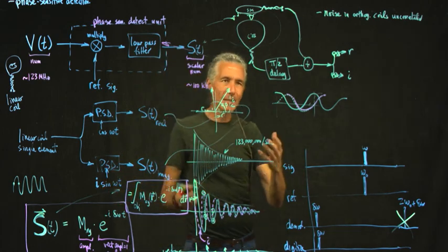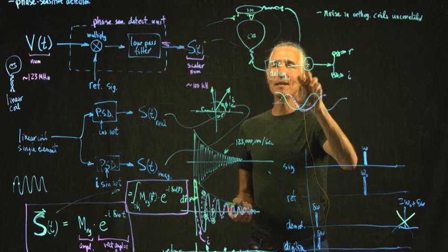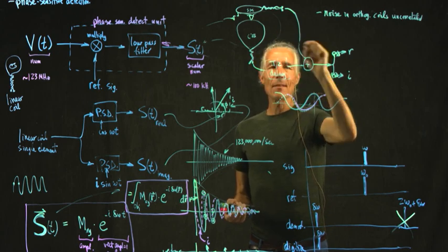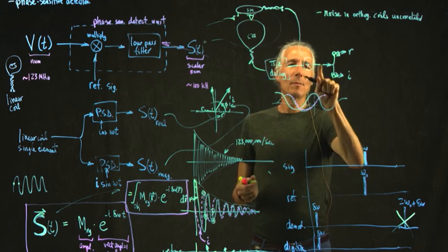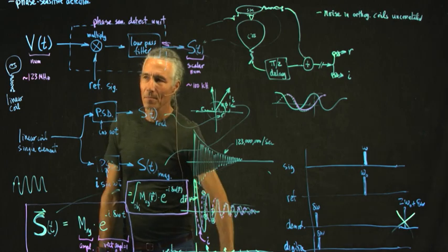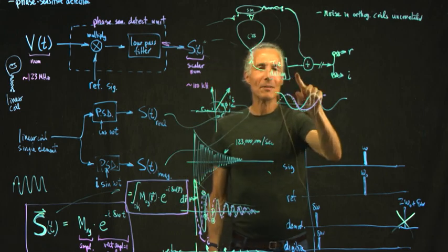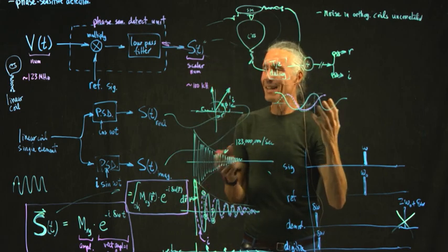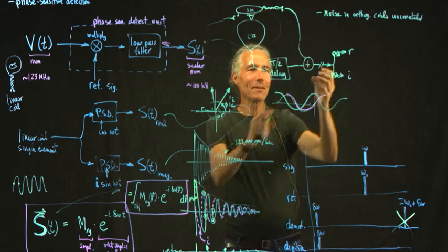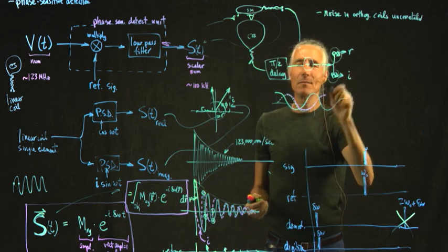So this is the way you might hook up a quadrature coil, and the reason is you just want to minimize the number of wires, because if you delay them and add them together, then you only have one. This could be a long wire heading to the phase-sensitive detection, and so you only have one wire. So you can understand that one. When somebody first said that this is the way it works, it's just like, what? You go through all this trouble to get two separate signals, and then you stick them together, and then you pull them apart again. But you don't lose anything doing that.